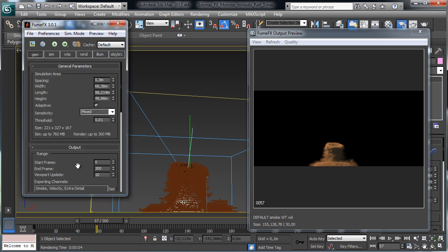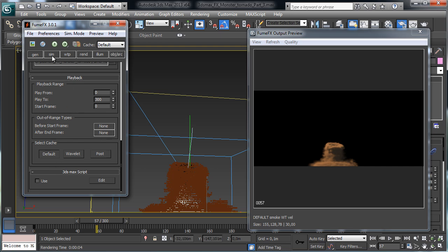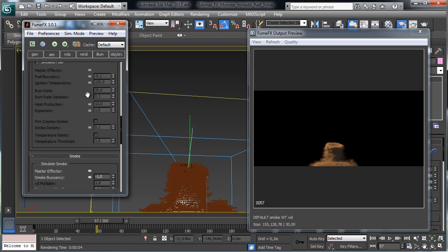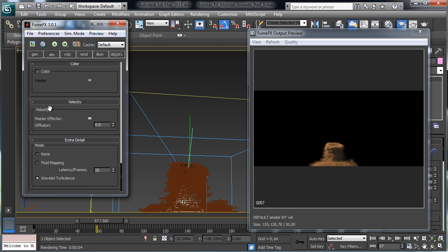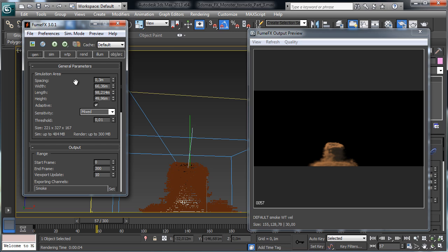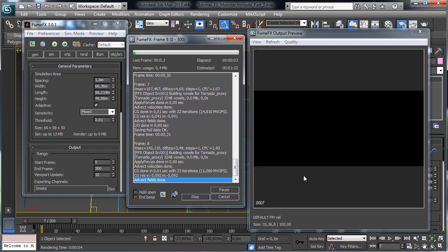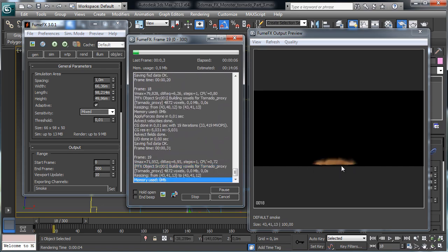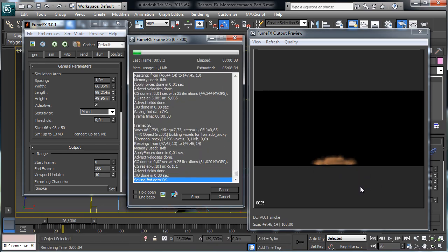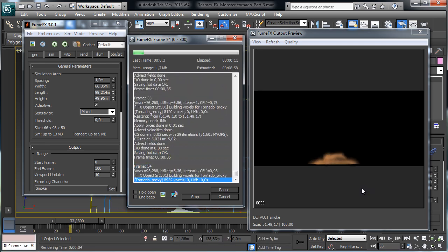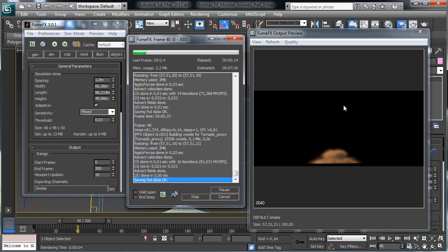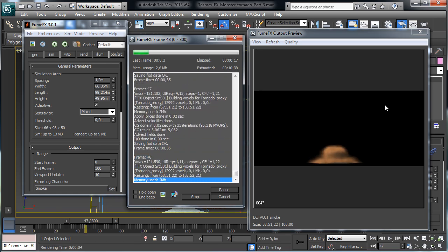Now I like to see what happens when we stay at the end to be sure that the simulation works completely. But to do this and to speed up things, I remove the extra detail, and let's remember that we have to use 0.3. Let's try to 5 times maybe 1. Let's simulate everything. It will be really fast in this way to be simulated. Obviously the quality is really poor, but it is not our main problem. I like just to see that when the object is moving, we have not so much trail.